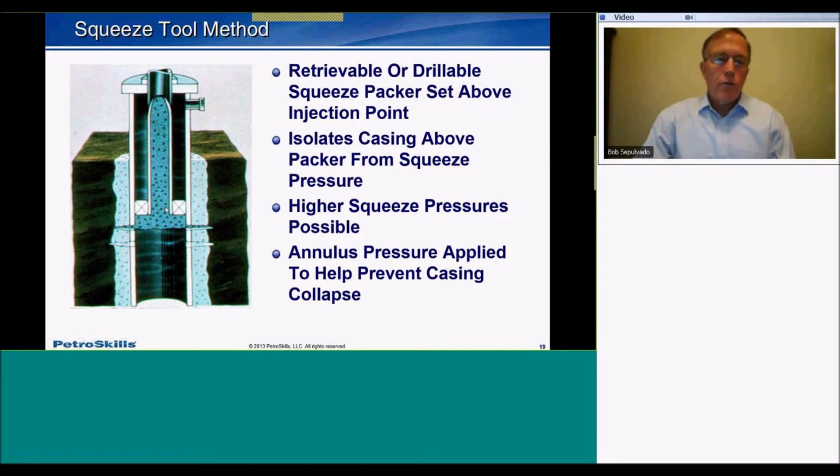The drillable packer is designed not to come out of the hole. It's a one-set, one-time packer. And when we're finished with the squeeze cementing operation, after we wait on cement, we're going to come back in and drill out and pressure test and check for competency of the squeeze. So since the drillable is not designed to come out of the hole, we can maybe be a little bit more daring with it, leave some cement on top of it,